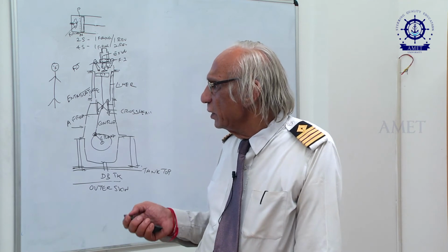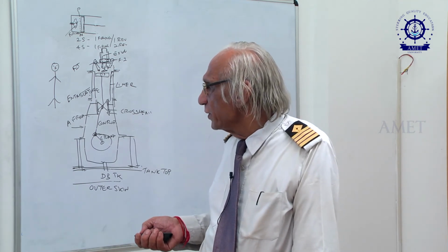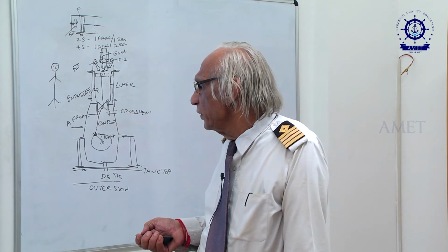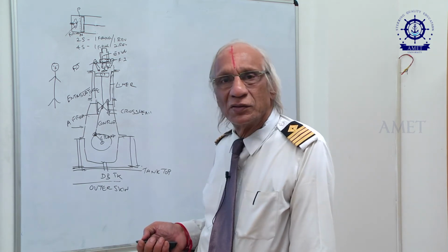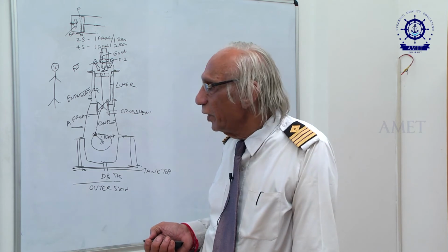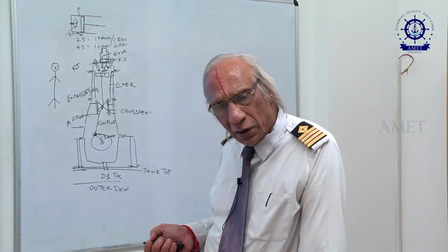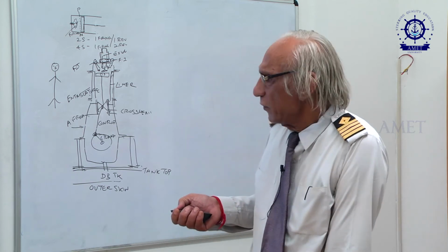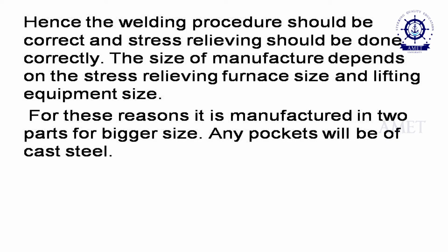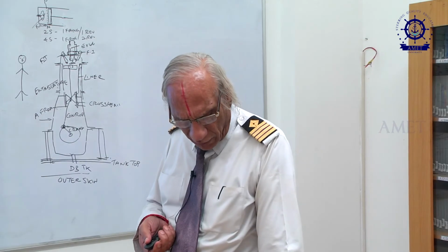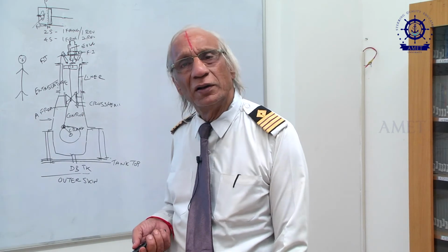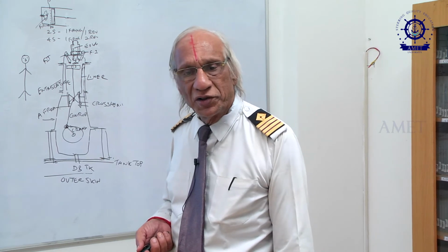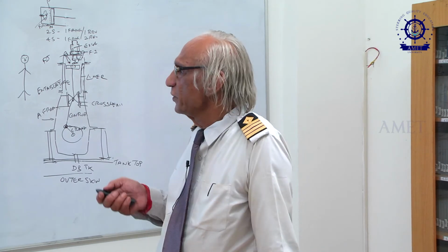But unfortunately, mild steel has a very low vibration damping characteristic. Hence, it is liable to crack on the welds. So this is one of the key defects we will find on the bed plate if the forces are not properly balanced and taken care of. Okay. Whoever does the welding of the bed plate, the transverse girder to the longitudinal girder, should be an expert, so that the welding is proper. At the same time, after completion of the welding, the joint should be properly stress relieved.